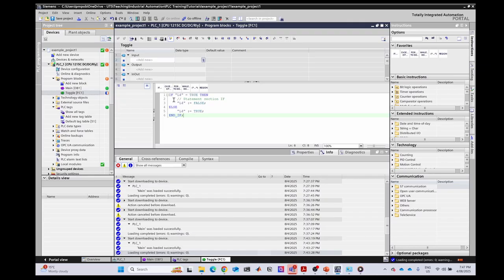What we want to do is just to toggle the LED number 4. So every time we execute this function, we will check if the light 4 is enabled, then we're gonna turn it off. And on the contrary, if the light is turned off, then we're just gonna turn it on. Okay. We declare the function, but we are not calling it in the main cycle or any cycle. So we are going to create a new cycle to call this function every 1 second.